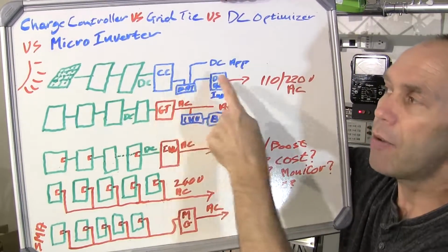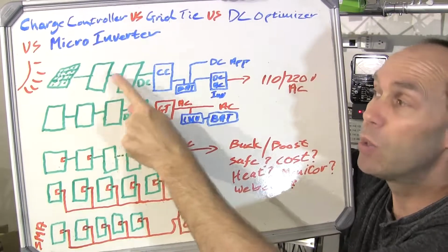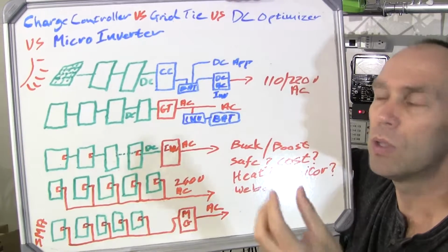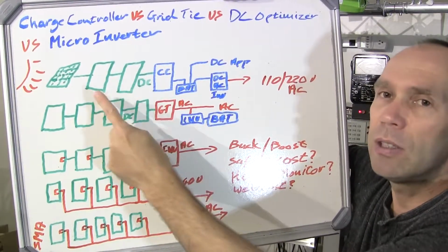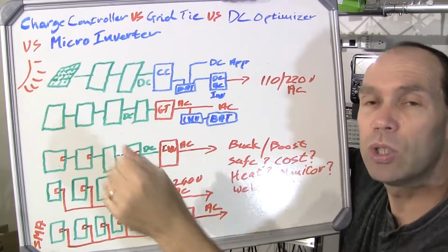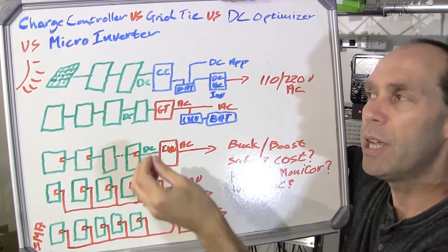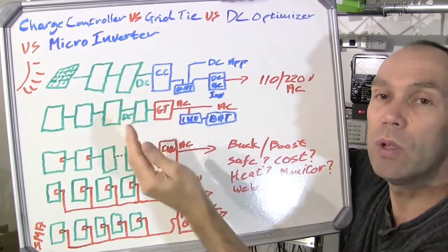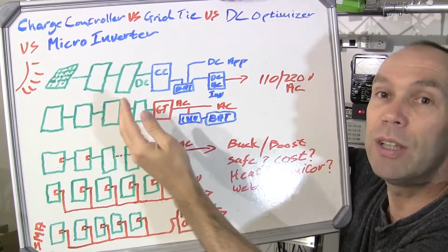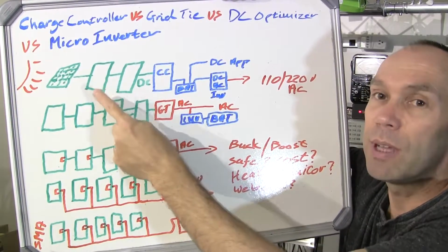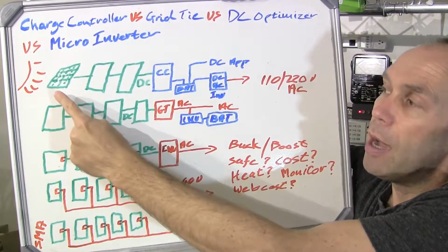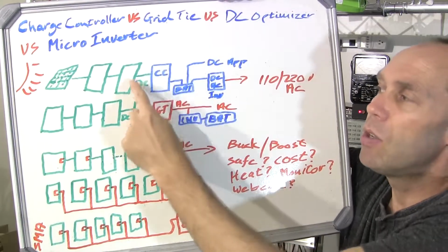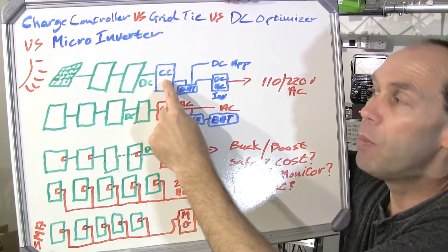Looking at this diagram at the top here, we've got some solar panels which are linked together in a string. This becomes important, because depending on how you link the solar panels together, whether in series, all chained together, or in parallel, potentially has an effect on the kind of voltages you're going to see coming into your inverter or your household, and also potentially the reliability and how well the whole system can function. Typically what you do is string a few solar panels together in series to get a certain voltage level, which is the optimum for the system.